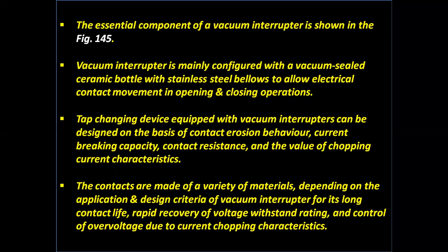The contacts are made of a variety of materials depending on the application and design criteria of vacuum interrupter for its long contact life, rapid recovery of voltage withstand rating, and control of over voltage due to current chopping characteristics.